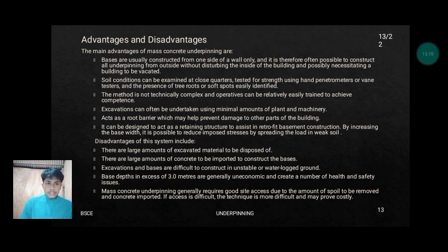And lastly, mass concrete underpinning generally requires good site access due to the amount of soil to be removed and concrete imported. If access is difficult, then the technique is more difficult and may prove costly.